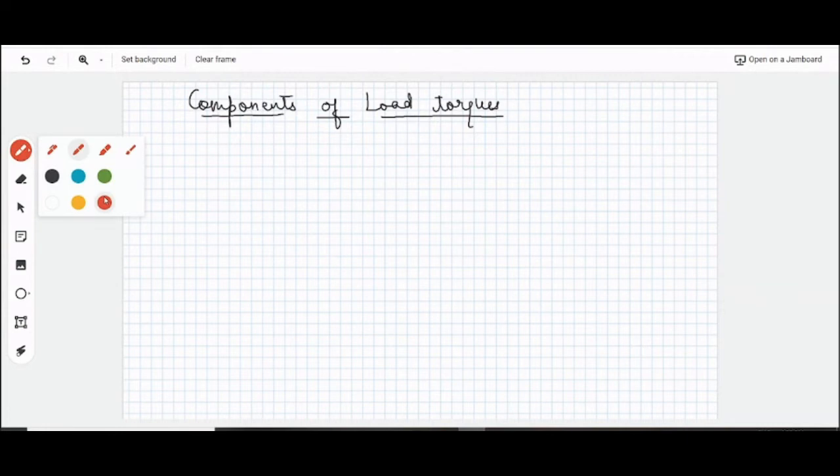See, we just have learned that your motor should produce a torque T_e equal to the shaft torque plus the dynamic torque if your drive is a constant inertia drive. We just have learned this, yes or no? And this is called the fundamental torque equation. Yes or no? Yes, sir. Someone please say something.